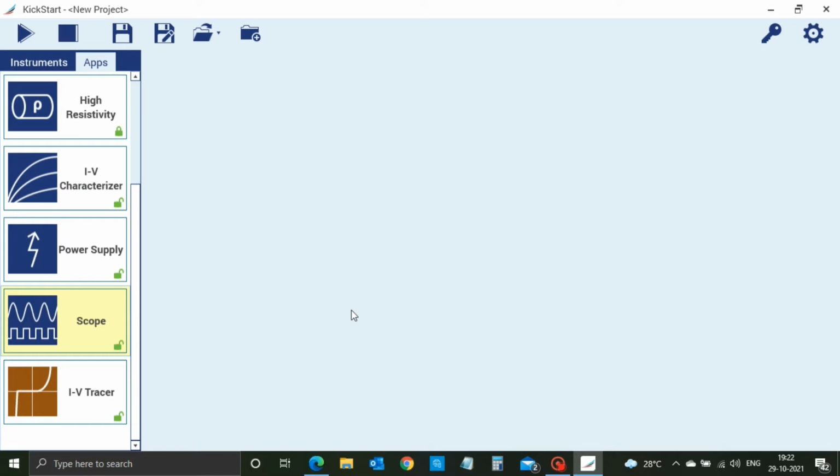Then the oscilloscope also has access to this software, where you can data log different parameters from the oscilloscope input channels, just like maybe from channel 1 you can log frequency, period, peak to peak, rise time, like that.